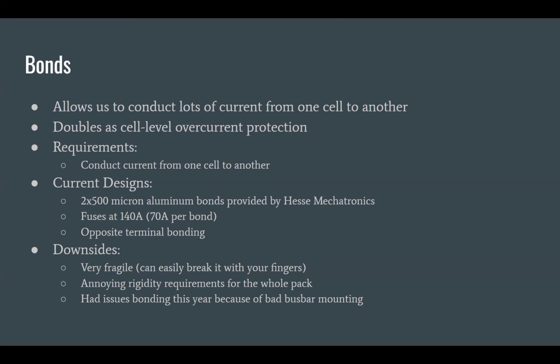Basically there is a rules requirement that says any voltage sensing connections in your battery pack need to be fused. There's a specific rule that says any voltage sensing connection in your battery pack needs to be overcurrent protected. That means you need to have a fuse on it, or some similar device, like a big resistor or whatever. So that's essentially why we have them.